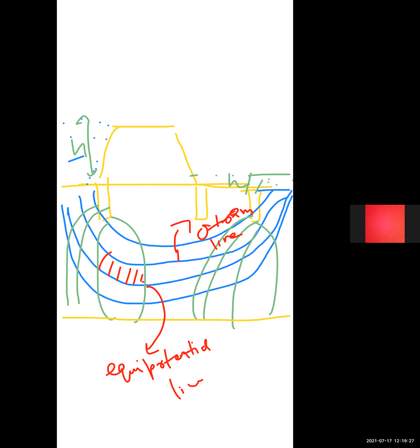In order that the soil particle at exit remains stable, the upward pressure at exit should be safe. In other words, the exit gradient should be safe. So for safety purposes, we have to study the safe exit gradient and critical exit gradient. Generally the safe exit gradient is 1 by 4 to 1 by 5 of the critical exit gradient.